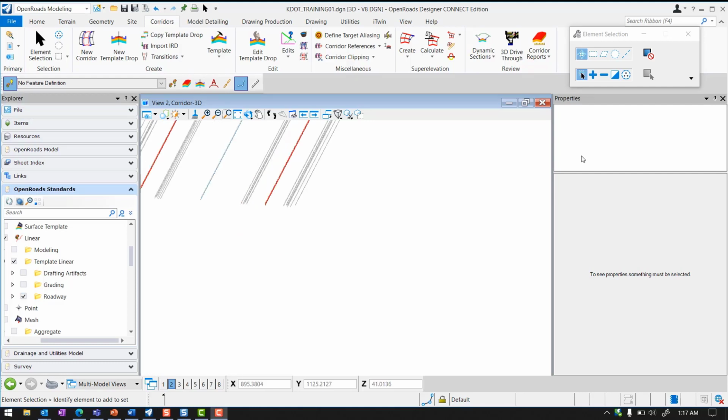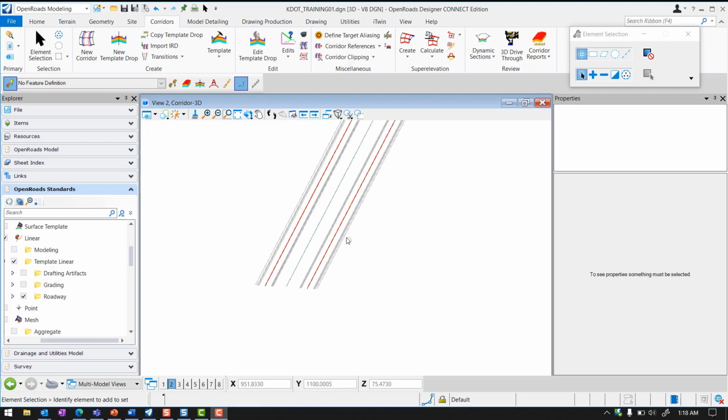As we mentioned previously, it's not uncommon to need to deliver a surface representing your top, bottom, or some intermediate layer of your design. There are a number of ways that you can go about doing this, but generally you're creating a surface from your break lines. Now, if you just had your break lines like you have them here, and we were left to try to manually select which ones represented a top or a bottom, it would be very difficult.